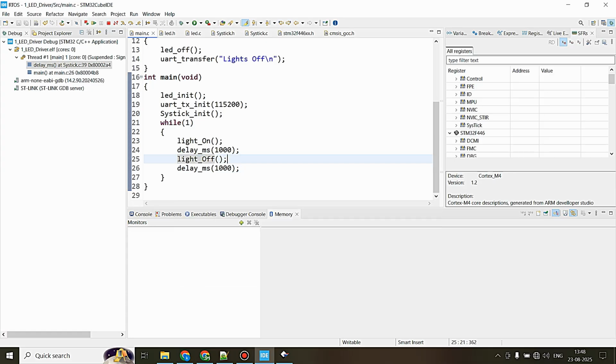So that is why in safety related applications, we instead use a parallel execution method instead of the blocking code method. This blocking code method is suitable for a simple application like a timer, counter, etc. But for serious safety related products, you cannot use this. It may cause serious issues to the product and also for the operator who is operating your product, or the person who is operating your product.